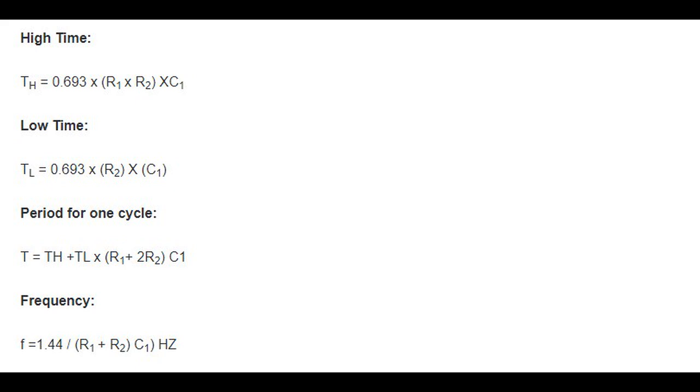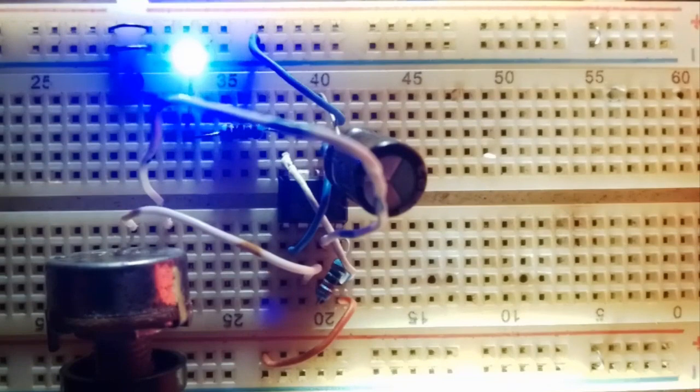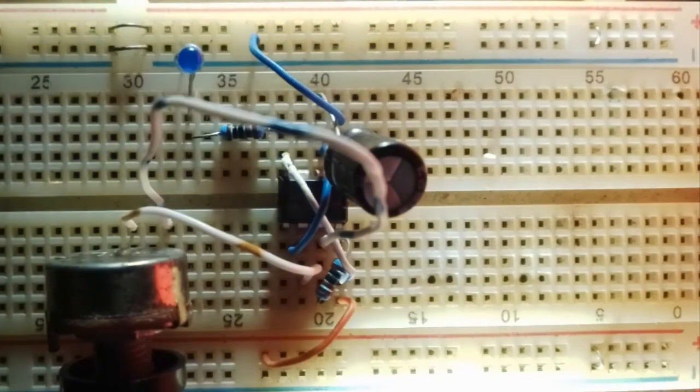And since R1 has the least significant effect on the circuit, we recommend choosing an appropriate value for it. Again, you can easily build a resistor network for any calculated value of R2 compared to a capacitor network. So, the rule of thumb is to always choose R1 and C1 for a given output frequency and use those values to compute R2.